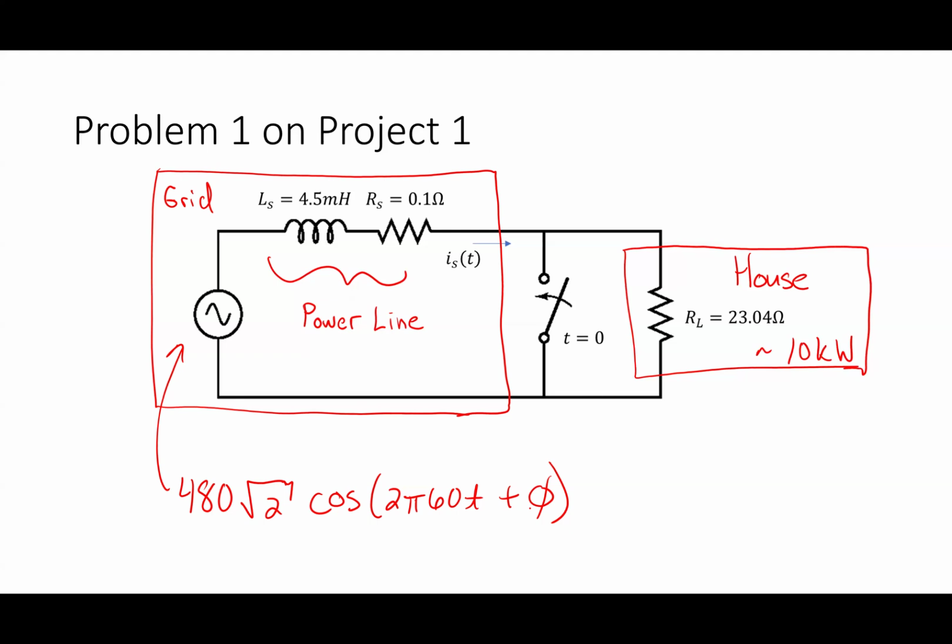All that we ever do is really analyze models. When you analyze a circuit, you're analyzing a model. A resistor, like you go in the lab and get a resistor, that's not just a resistor. It's a resistor and it's got some inductance associated with it as well. But inductance only matters at certain frequencies. In other words, if I put a gigahertz into my circuit, it might behave differently than if I put 1 hertz into my circuit. There's a lot to that, but this is the type of modeling that we would do.